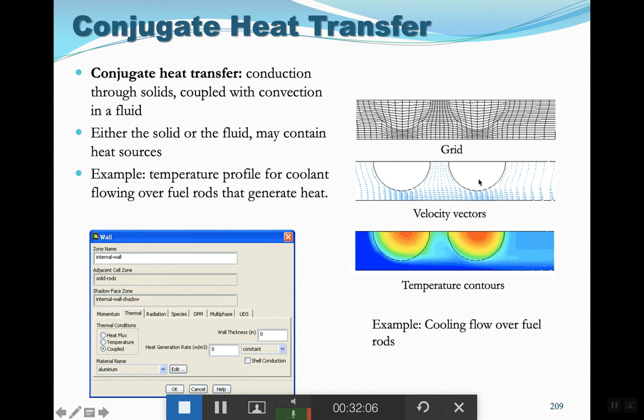The other method was just to carve out the two solids, so that your domain would be like this, and you wouldn't mesh the solids. In this way, the solids would act only as boundaries, and this is going to be only a fluid system. And basically, you're going to solve only heat transfer inside your fluid and not inside the solid.